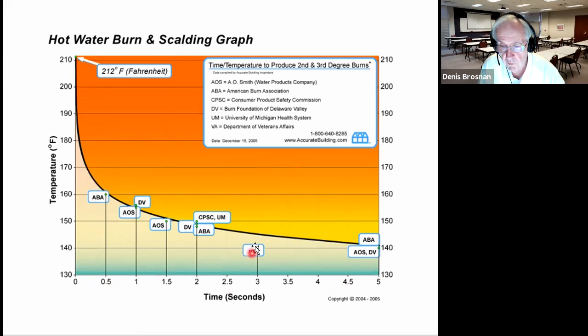But for longer durations of contact, if somebody grabbed a pipe or fell into a furnace wall from the outside of the furnace, they might be there a little bit longer. So typically designers will take into account scalding temperatures, and safety people will take into account scalding temperatures. If they measure a temperature on the outside of a furnace above a certain level, they may require a cage or a protective device to keep people away from that furnace.